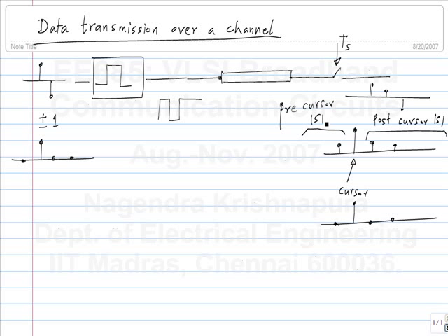It's named that way because anything that comes after affects the symbols that are transmitted afterwards. Anything that comes before affects the symbols transmitted before the current symbol. You can affect the previous symbols because you have a delay in the system. If the delay is more than one symbol, you can affect the previously transmitted symbol. So you can think of this as the response to a single pulse, a digital impulse response.